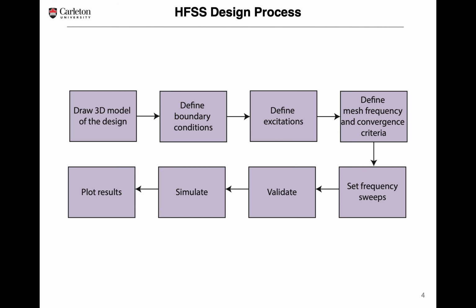So the HFSS design process is on this slide, and I want you guys to always, whenever you design something, go through this process to make sure that you've done everything right. So the first step is to design the model of your structure. So in HFSS, we're dealing with 3D structures. So it could be a combination of boxes or cylinders or surfaces. So the first step is to design the structure on HFSS, and it works like any CAD modeling software.